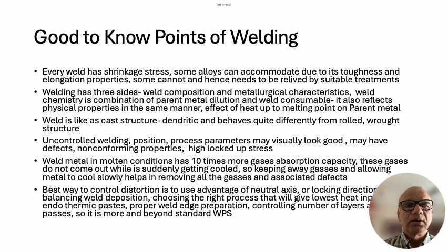The second is the parent metal itself, which is undergoing different heat treatments, because the different cross sections from the weld towards away from the weld will undergo different thermal cycles. Some of the cycles will be hardening cycles, some of the cycles will be stress relieving cycles, some of the cycles will be half annealing cycles, some of the cycles will be normalizing cycles. So each of the cycles on that parent metal is going to be different.